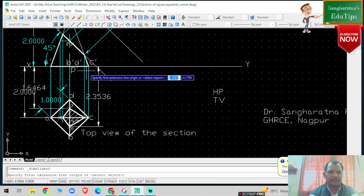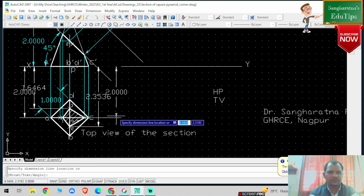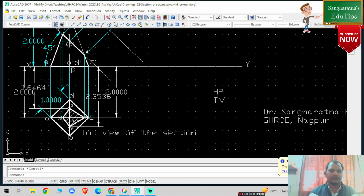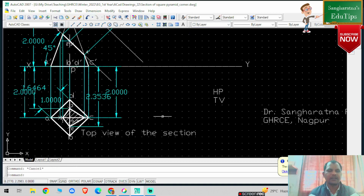Select align from the reference line to the projector line; this is basically 2 AutoCAD units. Now convert these dimensions into cyan color. The same dimensions we need to mark there. Press escape.